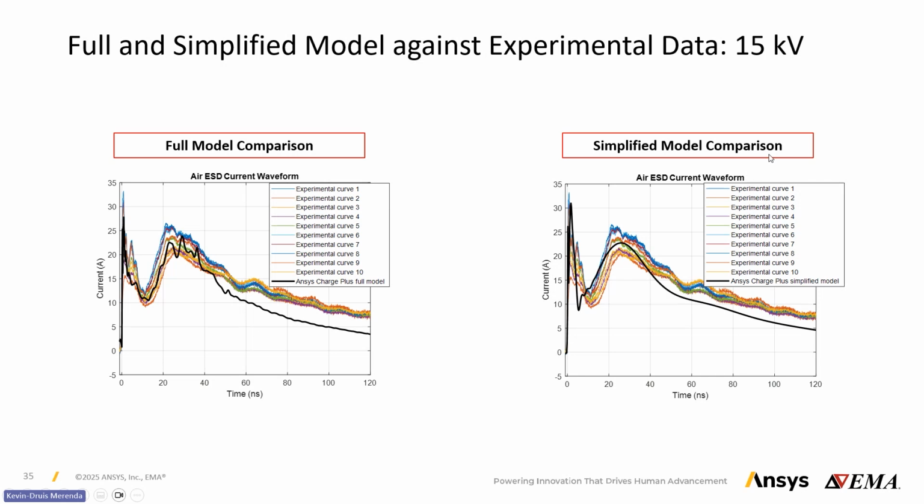And this is all done on a 2 ohm target for a 15 kV discharge with a fixed gap size. Ideally here, we don't have any motion of the gun. You can imagine that you approach the gun at a fixed distance, and then you discharge it by flipping a switch. And so it will be very consistent in the simulation, which might not be as consistent in your testing environment.